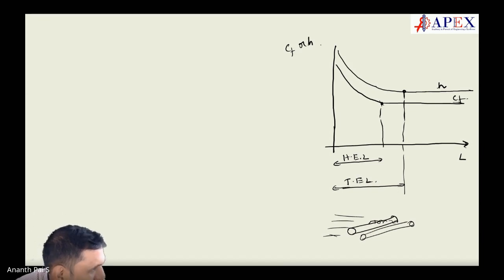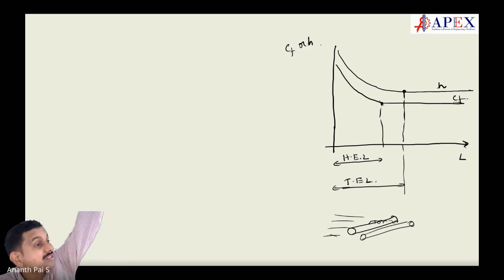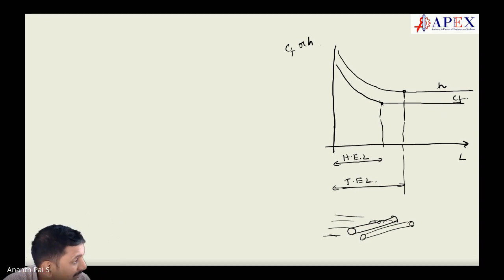So in a heat exchanger, what do you want? You want heat transfer rates to be changed. So these are the passive things. But then when you have this, what happens? Pressure drop increases. It's always a play between pressure drop and heat transfer. Pressure drop more means more pumping power. So it's all economy that matters.